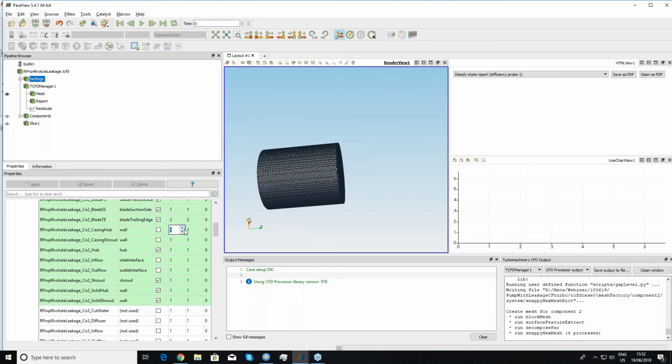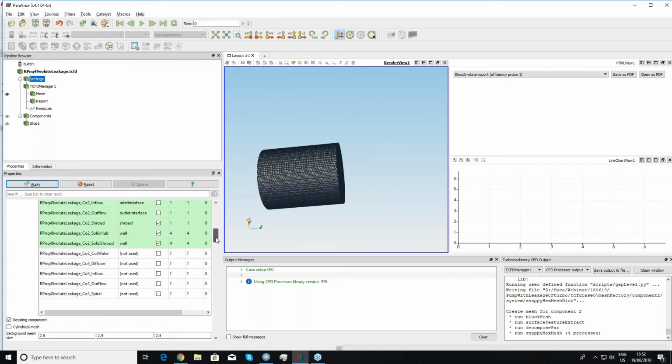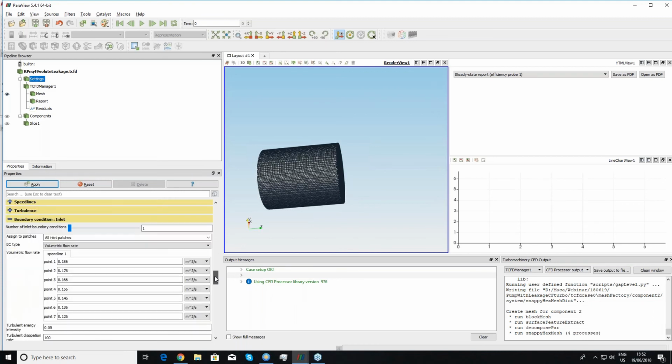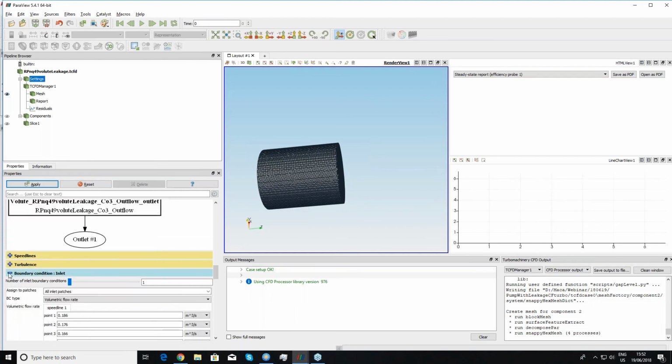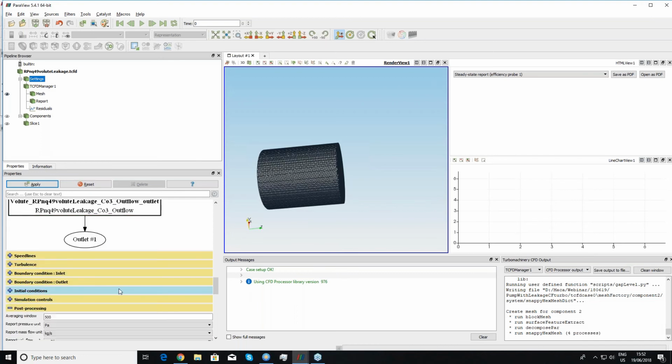So just increasing this number, we will get finer mesh at these parts. And because walls are merged together, of type wall, if you change it at one side, you will get the same number everywhere. So for example, if you would like to have really fine mesh, you can add it here together with the layers, of course. And the more advanced tool how to enable that, which is quite a smart tool for advanced users.